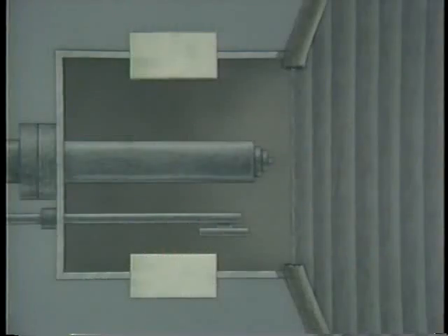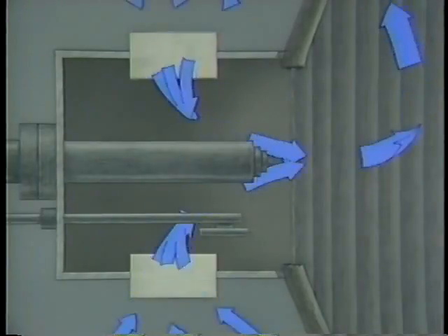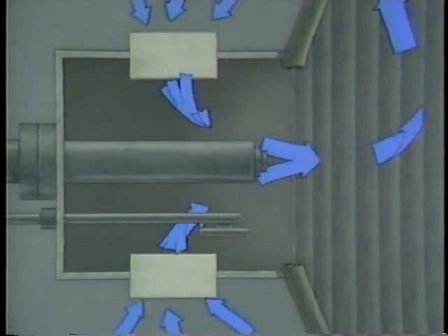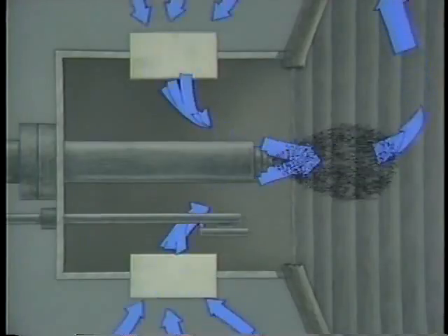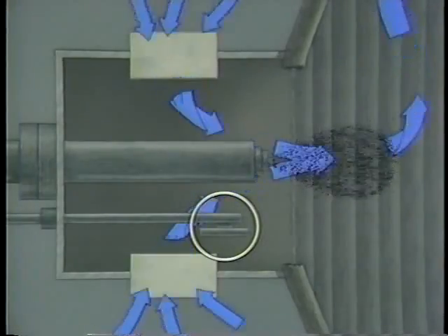Let's suppose that the igniter malfunctions and does not spark as it is supposed to. We'll use the same illustration to see how an explosion might occur. The operator turns the controller to start the igniter sparking. However, in this case, the igniter is slow to respond and doesn't spark right away. The operator next establishes airflow to the burner port and then starts fuel flow. The igniter still doesn't spark.